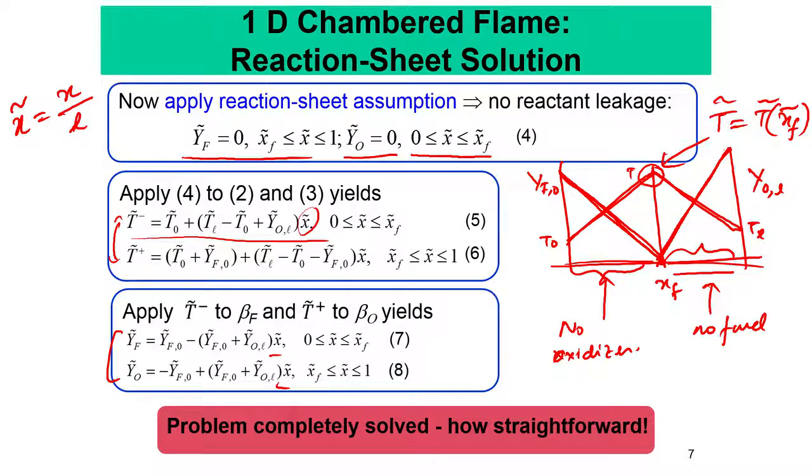So you see how straightforward it is. This problem contained all the complexities, right? It contained the reaction rate, etc., but we just removed those things by using the coupling function formulation, and as a consequence of Lewis number equal to 1, we solved this whole thing in just one step, by forming a Laplace equation out of these complicated diffusive reactive equations. So that is the strength of coupling function formulations.